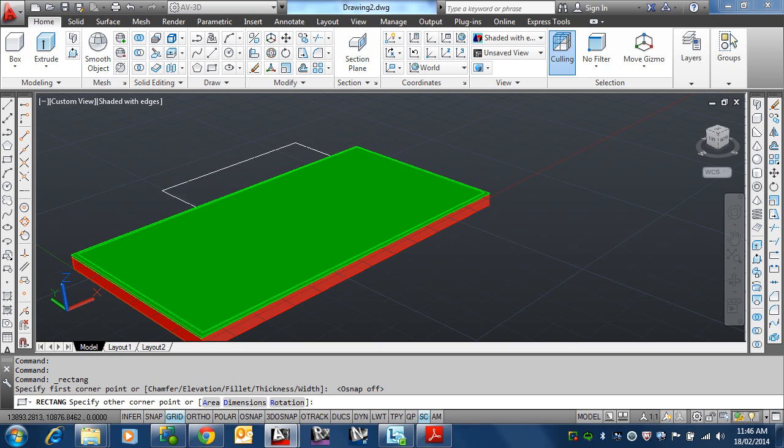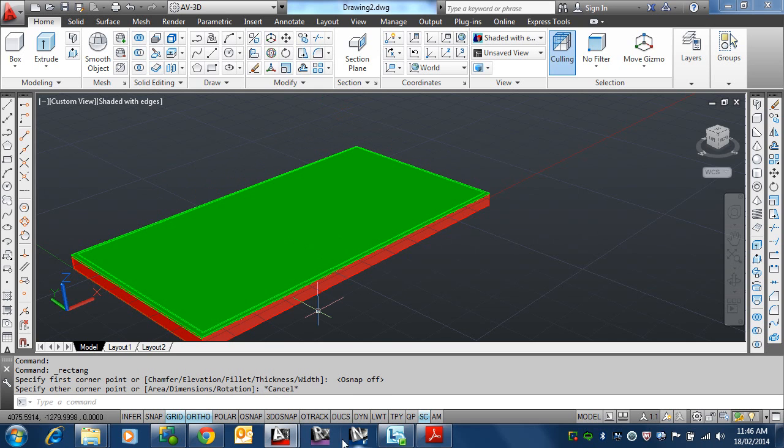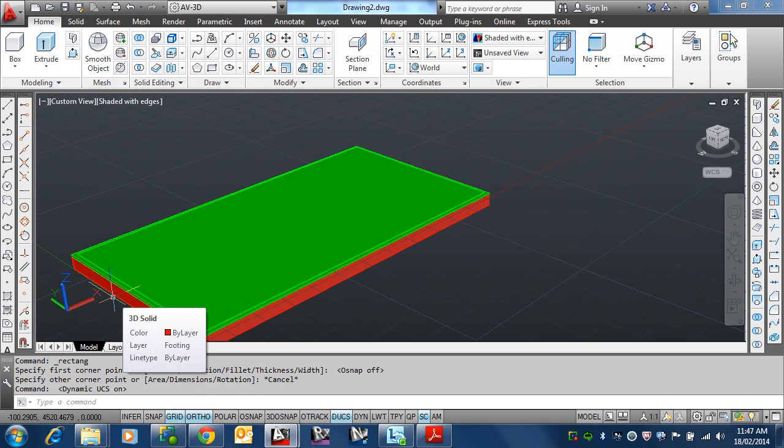size that we want. Now note, it doesn't look like it's picked up anywhere, but if I move out, it's done something. So it seems to be drawing it underneath, which is a problem I have had in the past. But that's fine as long as you recognize where it's drawing it. It's not drawing it on top. Okay, so perhaps in this instance we should escape that and put this dynamic UCS on, and we might be okay. We'll see. So, as I said, the UCS is in the world format, which means it's drawing it on the grid, on the flat.